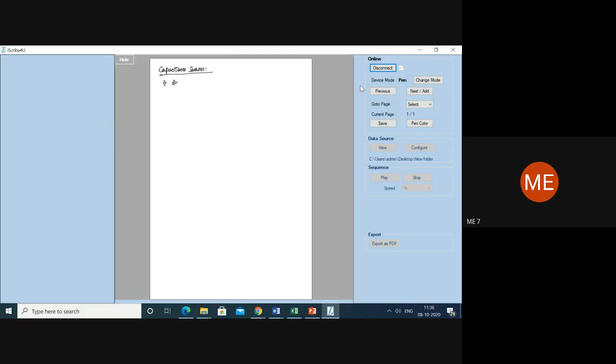One is by moving the plate in the y direction. Correct? This is the first one, and this plate you are going to move. So this is one method. The second method is by moving the plate in the x direction. Now in the first case, which parameter of the basic equation changes? Area? Distance between the plates. The distance between the plates, d, changes.